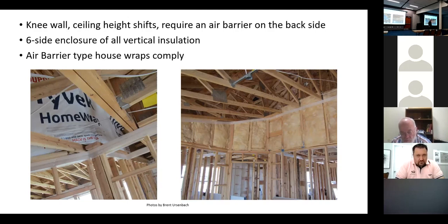You've seen that. Yeah, we did it on a tiny house that we were building as a company, and I did the details for the roof system. So we did 6 inches of polyiso, we used 1x wood battens at a 45-degree angle to create a ventilated drainage plane, and then standing seam roof on top of that. So, it works really well. It's a great system.